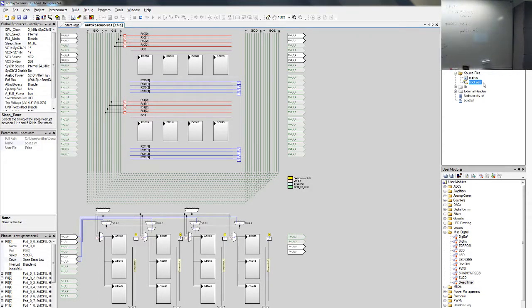Okay, and then when you build the project, basically it makes this downloadable hex code that you can program the chip with, to run the boot code first and then call the main function. Okay, so if you ever thought about why on earth in C programming we call even the main program a function, it is a function. Okay, anyways, what else did that clicking actually do?